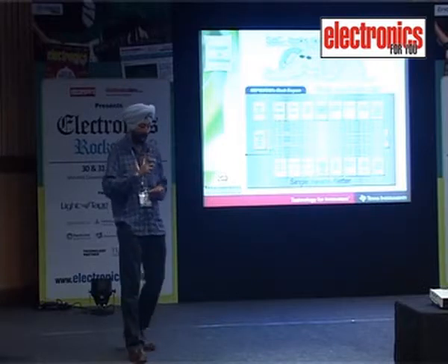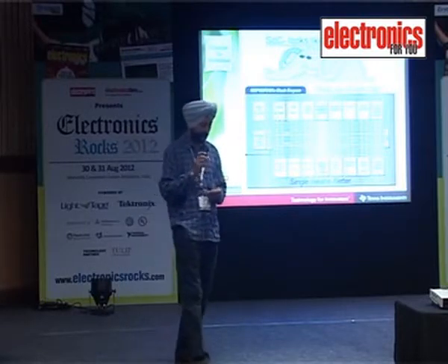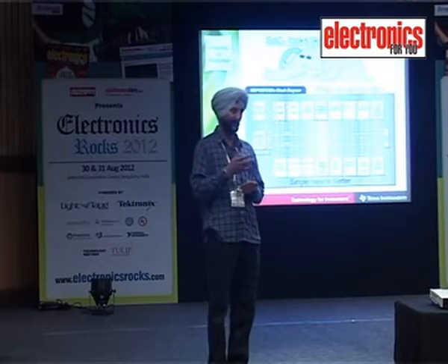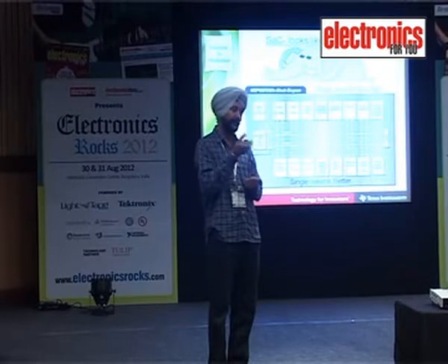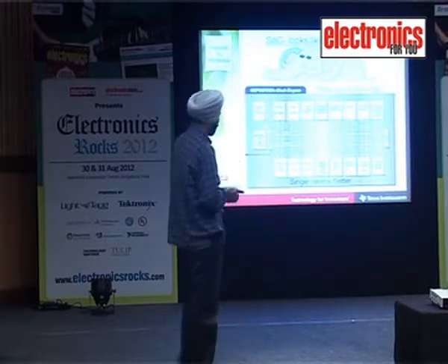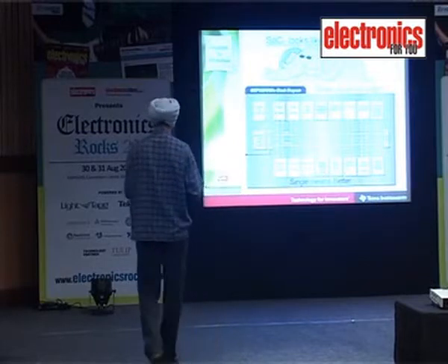of the particular data because when you are transmitting some information through wired communication or wireless communication, at that particular time you can switch to the crystal, and again you can switch back to the DCO, where frequency variation will not affect your performance of the system.